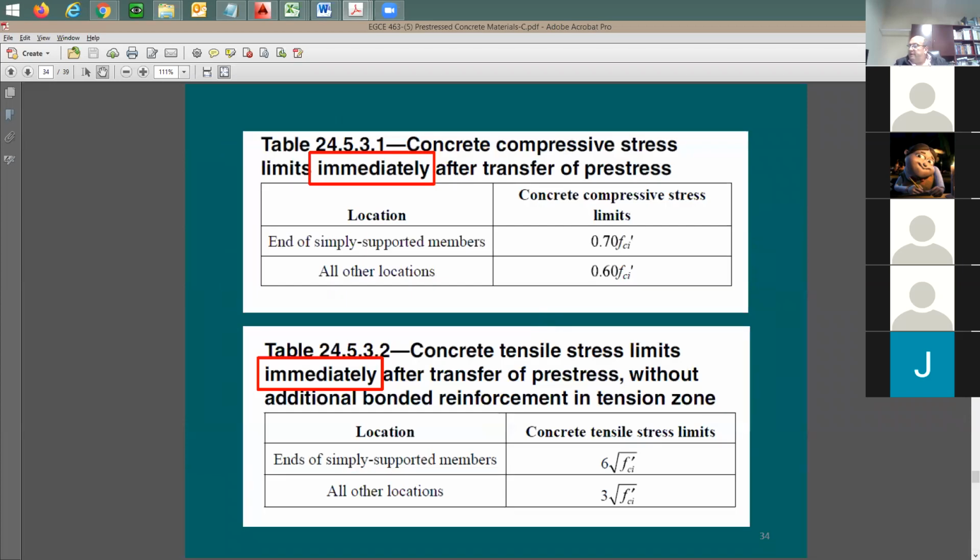All right. I guess now you have an idea about the exam. Any questions for me? Are we having any conceptual questions for the exam? I just went through this already with you guys. Here's one of the questions. If the tensile stress is equal to 6 square root of f'c in the beam, would you consider it to be cracked or uncracked? Uncracked. Okay, I guess you answered one of the conceptual questions.